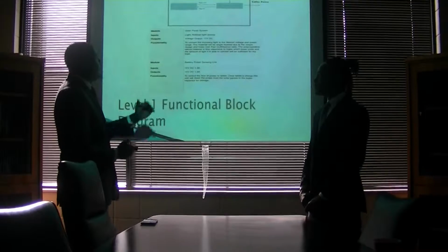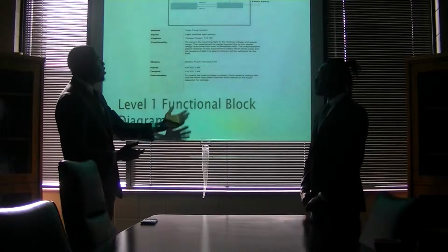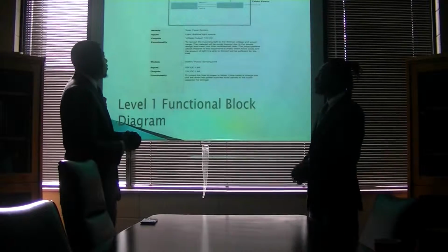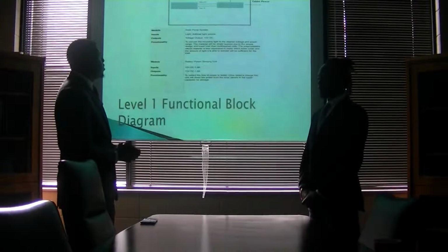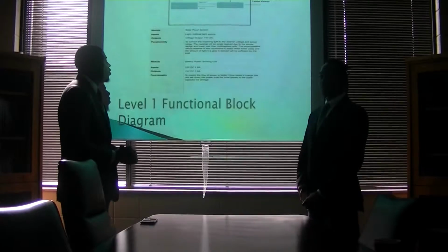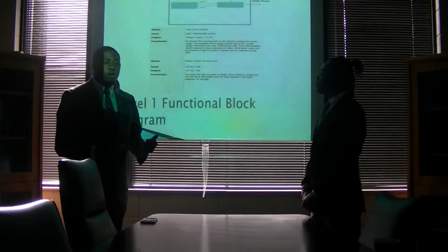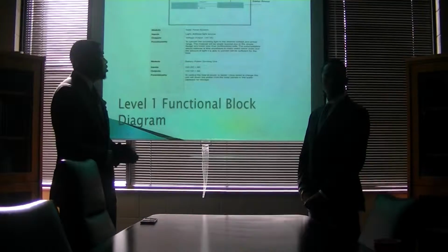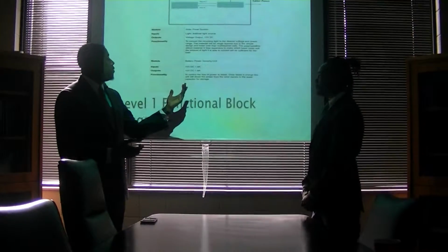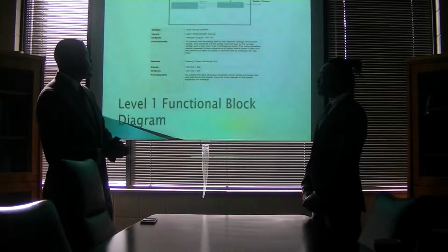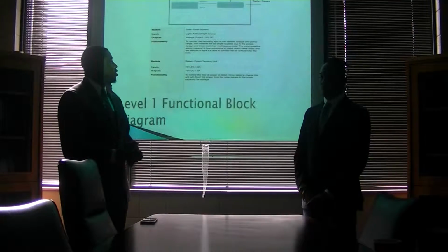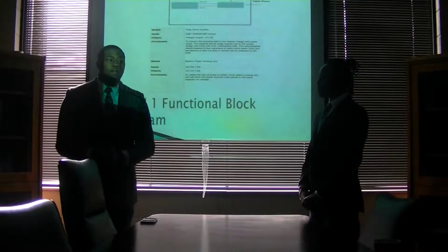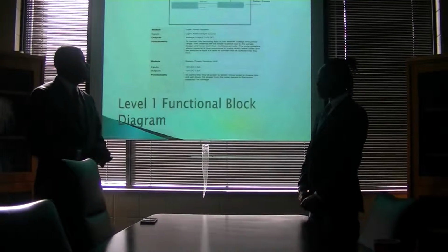Again, our modules have a solar panel system receiving an artificial light source, with 15 volt DC coming out. This is used to convert the incoming light to the desired voltage and power range. The material will be single layered due to the simple design and lower cost than multi-layered cells. The polycrystalline silicon material is less expensive to make, which is lower cost, and the amount of light it is able to convert will be sufficient for the load.